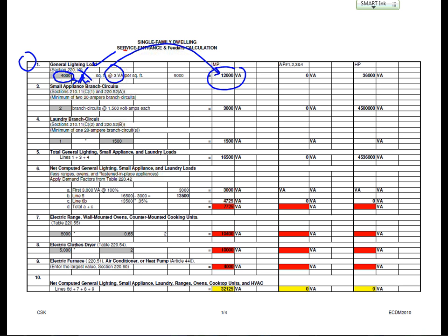Your apartment, guys, also has to have a square foot for it. So you take the square foot of the apartment, multiply it by 3, and that will get you the volt amp allocated for all the lights and the receptacles based on the NEC code book for every apartment. One more time. The first calculation is related to the convenient receptacles and lights in the apartment. The code says, guys, for these convenient receptacles and lights, take a 3 volt amp, multiply by the square foot of the apartment, if you're doing apartment, of the common place, if you're doing common place, right? Of the whole building, if you're doing the whole building.